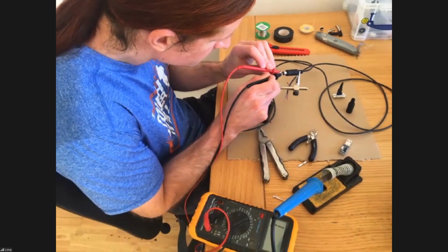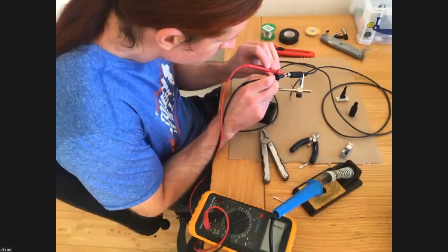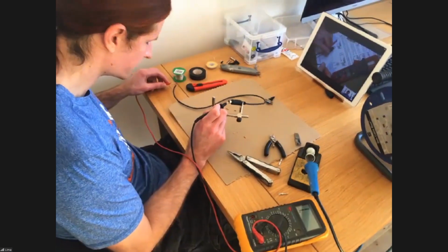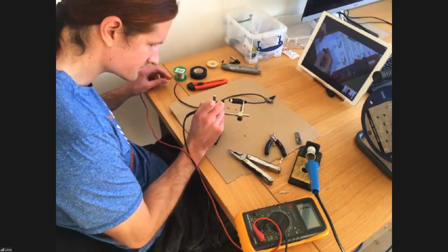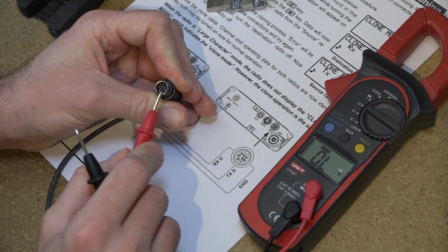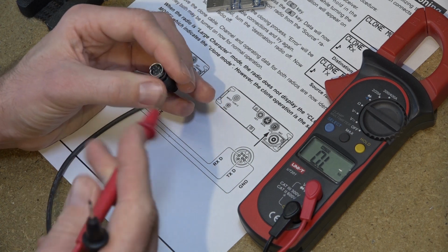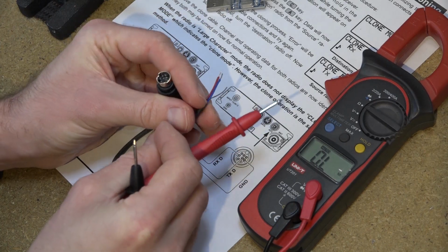Is it worth checking now that nothing's shorting? Yep, that's a great idea. So if you've got a multimeter, you can just check between each of those pairs of conductors, and none of them should have continuity. You can also check between each of those bare conductors and the pin at the other end. Remember, if you're looking at the connector from the front this time, they're going to be the opposite way round. So your ground pin, as you look at it from the pins, is going to be on the left. And your receive and transmit data are going to be in the middle and on the right.